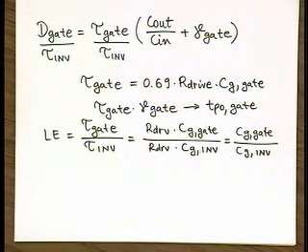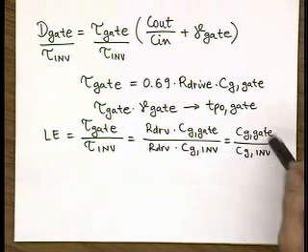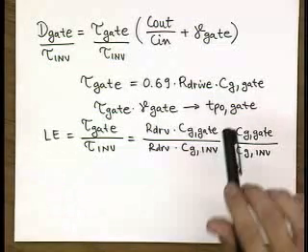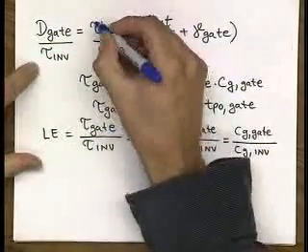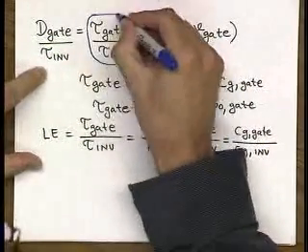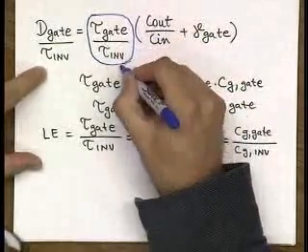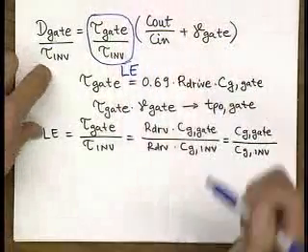You remember what we did last time for an AND, when we had a stack of 2 transistors: we have to upsize the stack transistors to make sure they have the same equivalent resistance. That comes from this fact. This is just a pure definition of logical effort, and it is an important term. So now this is our logical effort.